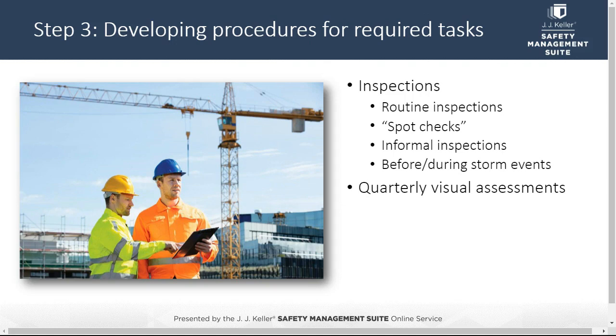Last, keep in mind that all SWP inspections are only as good as the inspector. Therefore, it is important to select qualified personnel to conduct your inspections. Be sure to identify who that inspector will be in your SWP. Personnel selected should be knowledgeable in the principles and practices of stormwater control measures and identifying conditions that could impact stormwater quality.